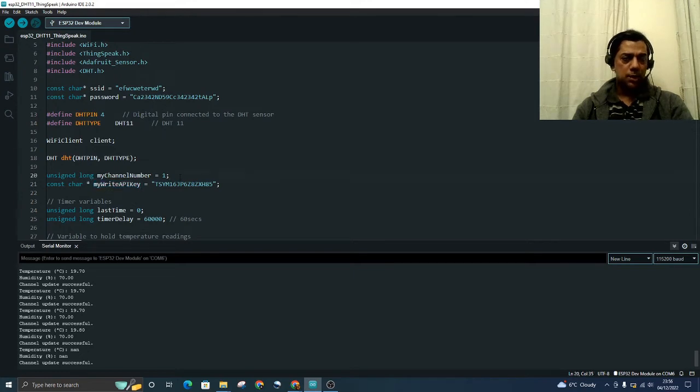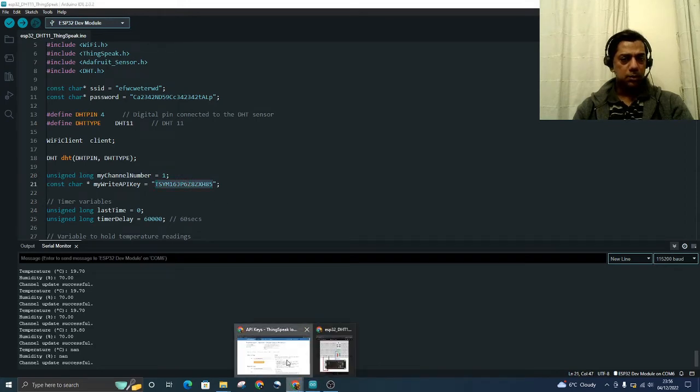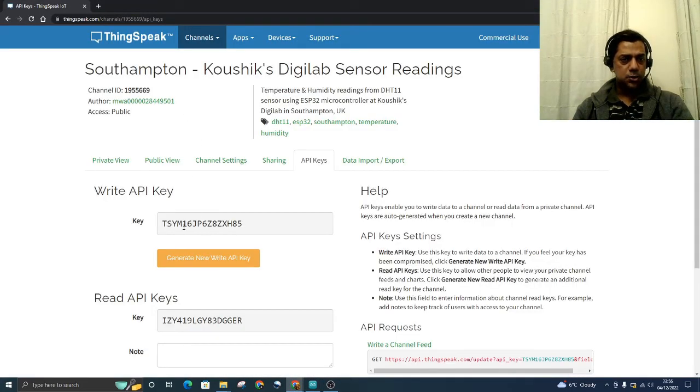So currently I have only one channel in ThingSpeak. That is why my channel number is 1. If you had multiple channels, you would have to set the channel number accordingly. So this is the same key which I have configured in the ThingSpeak channel. So I will be using this key to post the data. Okay.